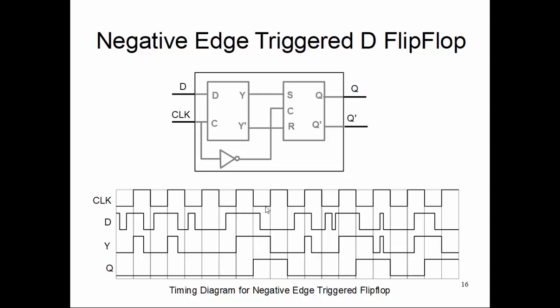Basically, this data transmission or data handover between S and Q is just turned off when the clock goes to high, so it stays at high. Now next clock down, Y becomes 0, so it goes down. So you see, basically it is selectively passing the value of D onto the Q,